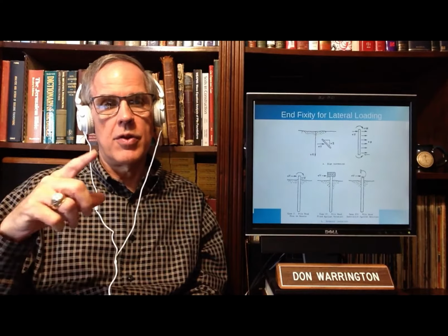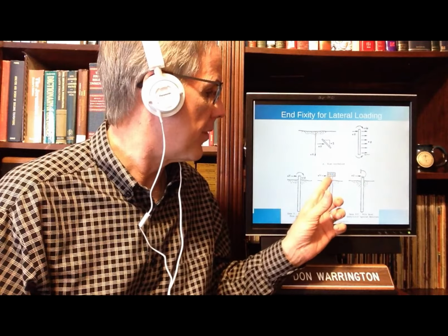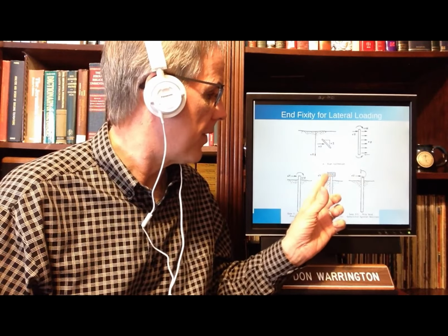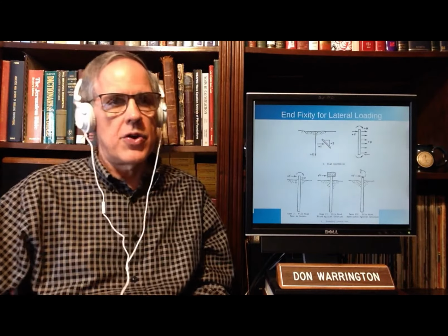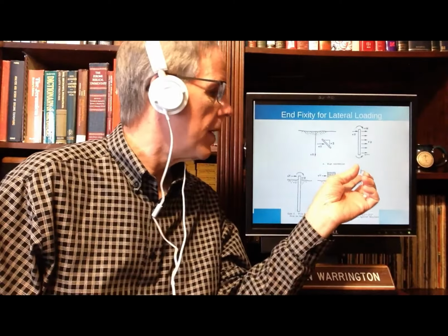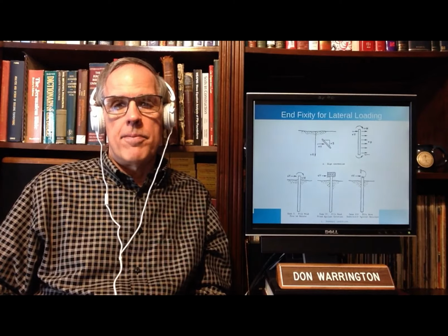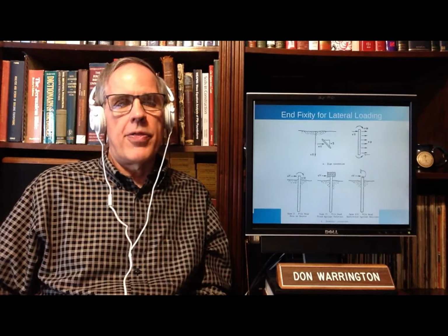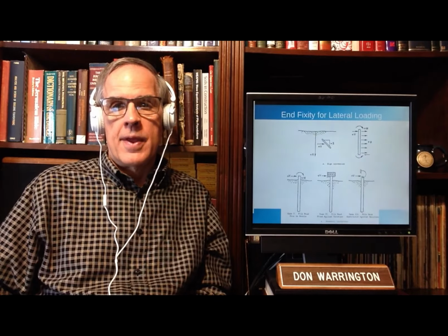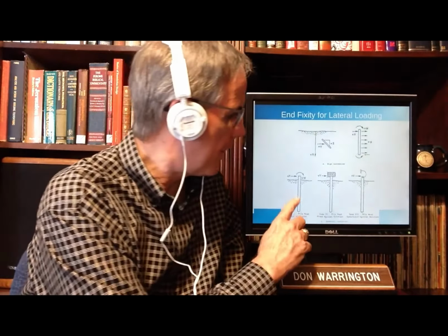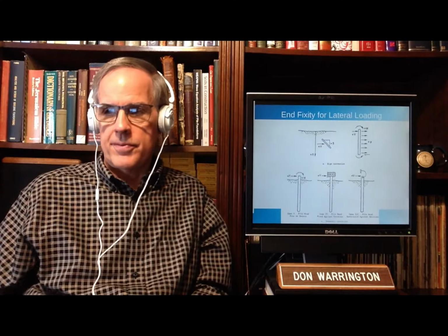It cannot rotate. In other words, the theta up here at the top is always 0. There's no angle of rotation allowed, and that's what these rollers are all about. It's also possible to have, say, a torsional spring acting at the top, where the beam does not rotate. We're not going to worry about those, but obviously those are significant for certain types of structures. These two are the ones we're going to look at, the free head and the fixed head. That's the distinction between the two.